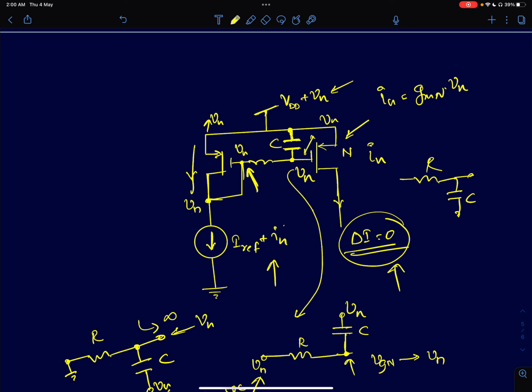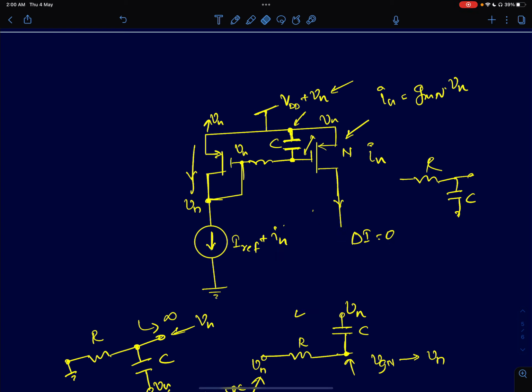Okay, so that's it. That's the reasoning why I was showing the capacitor between the gate and the supply. So such capacitor arrangements are called supply referred capacitors. And there is another reason. It's much simpler. So generally, I've already said this in one of the previous lectures.